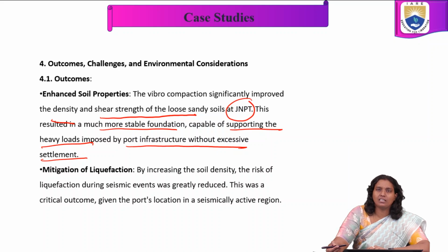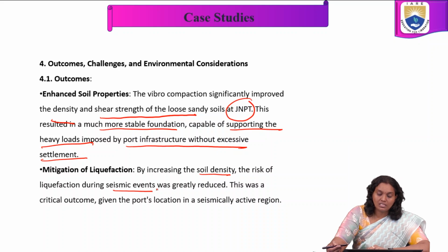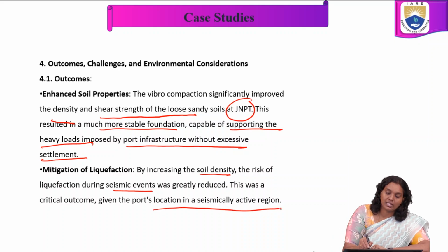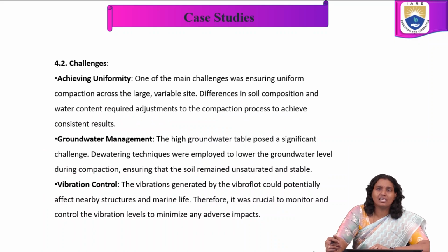Mitigation of liquefaction by increasing the soil density. The risk of liquefaction during seismic events was greatly reduced. This was a critical outcome, given the port's location in a seismically active region. Now the challenges: achieving uniformity, groundwater management, vibration control.